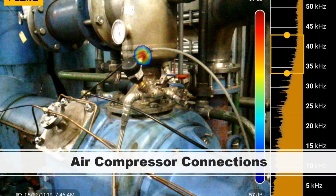By the way, those quick connects are notoriously known for having bad seals, because the idea is they plug them in and out all day long and swap tools and things like that, and the stuff just wears out over time, especially if you have really inexpensive ones. Things like this is a simple push connect for a tube. This could be a frayed tube end. This also could be the actual connect itself that has some bad barbs in it. It's just not grabbing good enough. Either way, it's just sitting there leaking air.